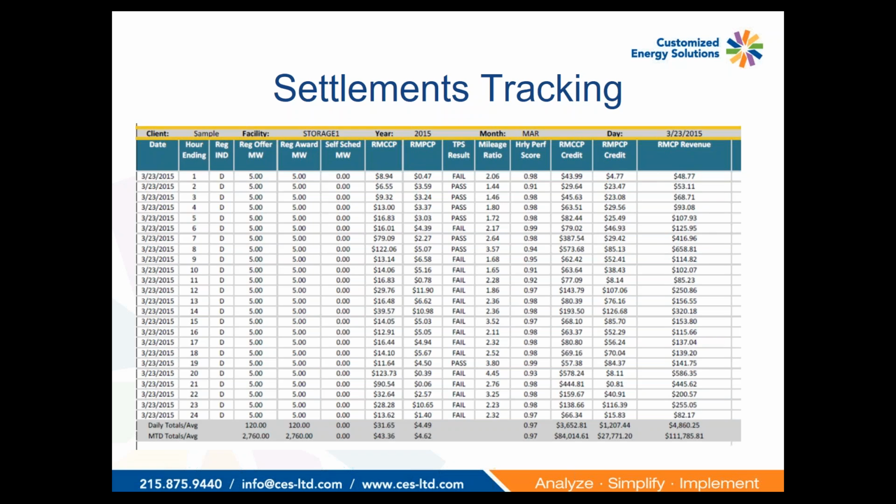And another one is the precision score, which measures the error between the response and the signal. There is a formula, which is 1 minus the absolute value of error divided by how many intervals you are measuring. So you have the correlation score, delay score, and precision score, and the average of those is the performance score. And there are some nuances to that.